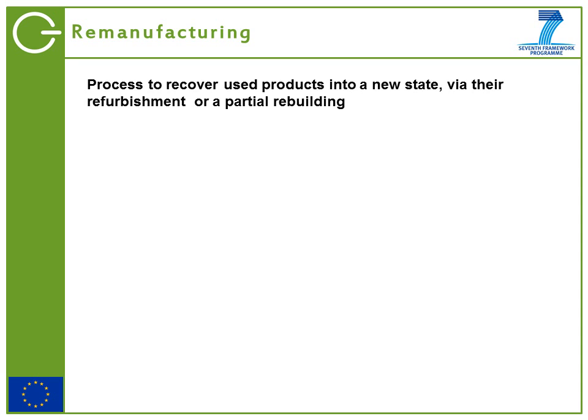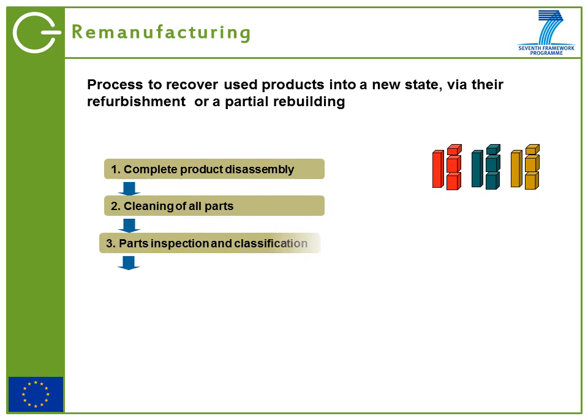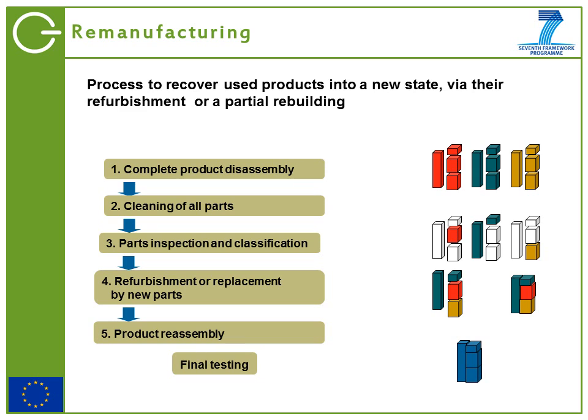Remanufacturing a product is about rebuilding a product from an older version and improving its performance. The first part of remanufacturing is the disassembly of the product. Steps 2 and 3 are about assessing the ability of the component parts to be reused and repaired for a second life. The parts are cleaned, inspected, and classified as usable or to be discarded. The usable parts are then refurbished and assembled together with any required new parts in order to have a fully functioning product.